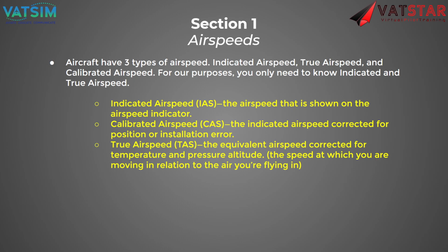Yes. I'll explain it like this. Let's say an airplane stalls at 55 knots. The airplane will perform according to indicated airspeed, because the airspeed indicator is showing basically what the airplane thinks it's at. So the airplane will perform according to the airspeed indicator. If you stall at 55 knots, you will always stall at 55 knots indicated airspeed. It doesn't matter what the true airspeed is.